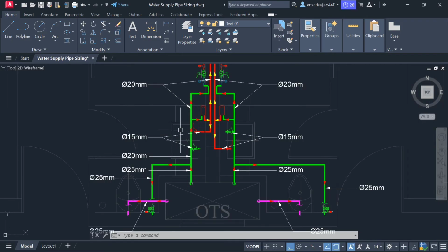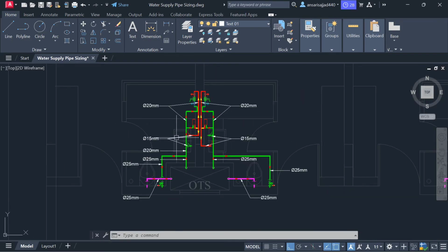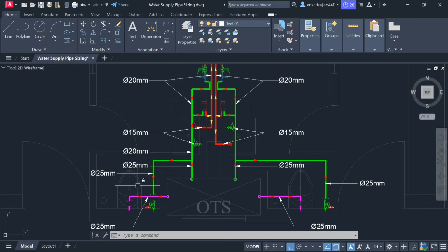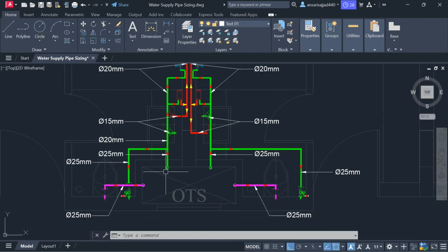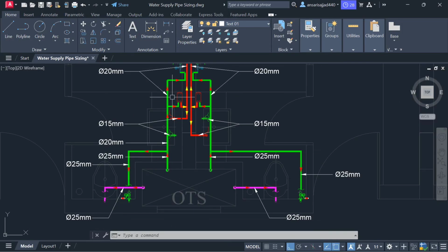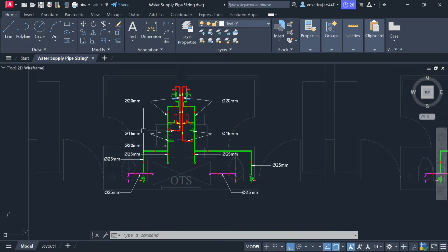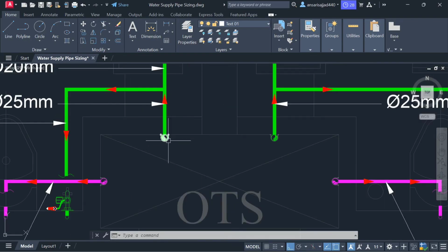So here you can see, if you remember, I told you the total fixture unit when you add the wash basin fixture unit, the shower and the water closet. We have got 3.7 fixture units. So if you multiply 3.7 by 7 floors, you will get around 25.9 total fixture units. Okay, I'm talking about this domestic water pipeline. For each floor 3.7 fixture units when you add all the fixtures. So total we have 7 floors which are typical. I'm doing the sizing for the riser.